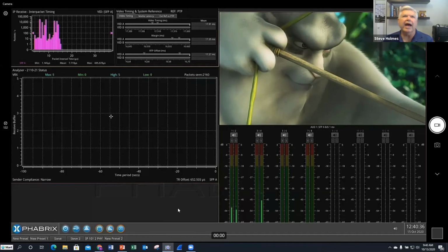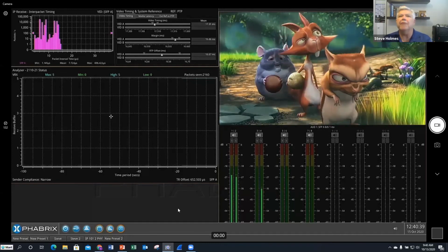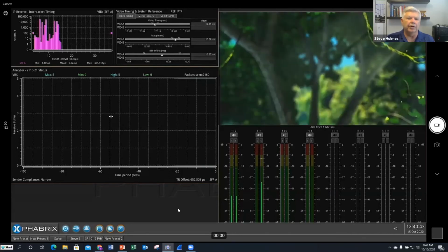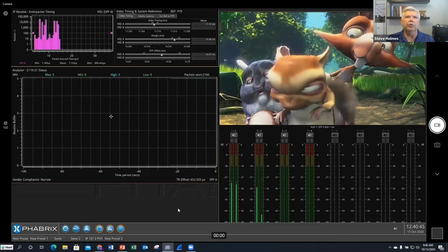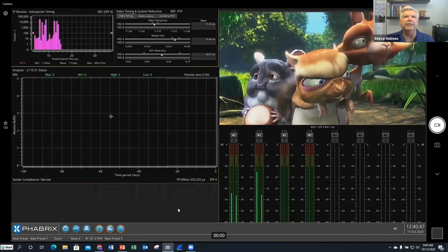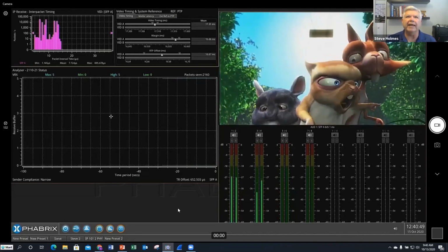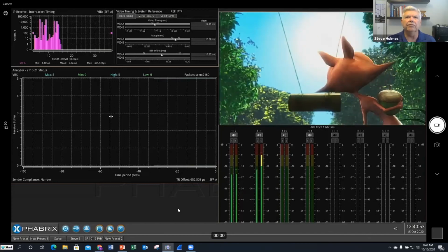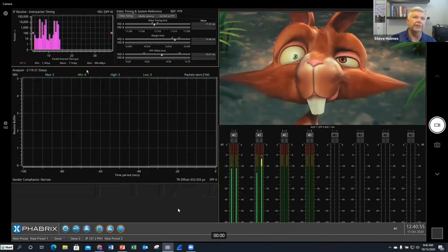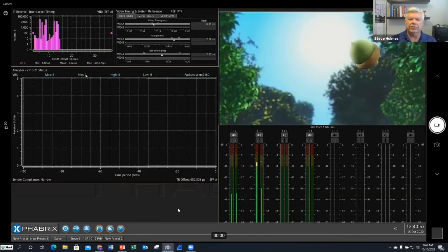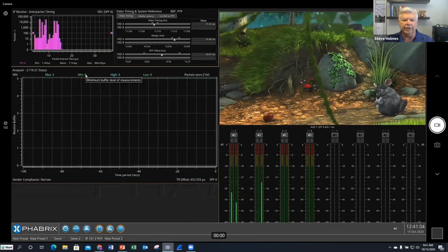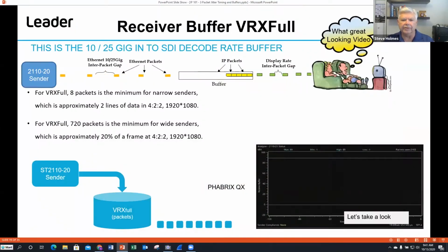So it's looking at roughly about 5 packets for my decode buffer, going from 10 gig down to 1.3 gigabits. I'm having to buffer roughly 5 packets. So it's well within the 8 packet limit of what I have going on in this system. So both devices do the same exact measurements, just slightly different ways of doing things here and getting through this.